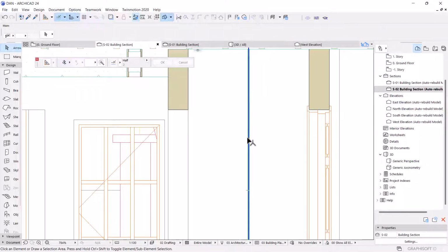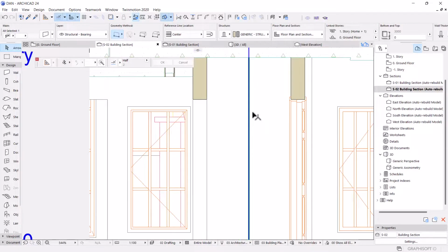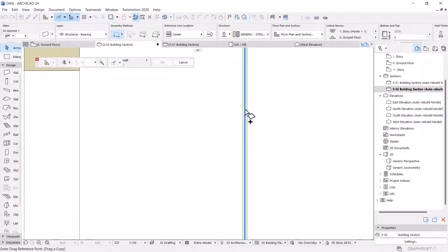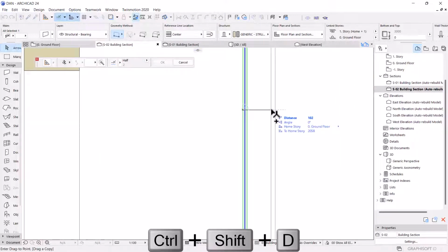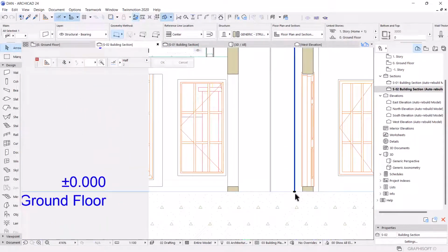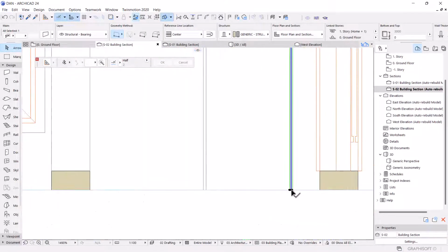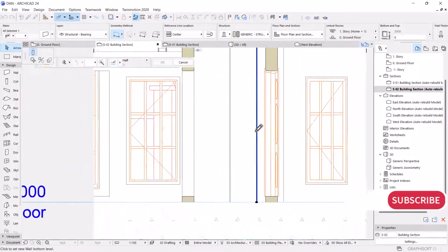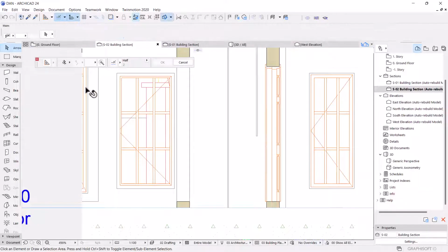Okay, so I can drag this one to the right. Let me drag from the center so that it is 900. The half of 900 is 450. 450, then I can try to shorten it. So you can draw this with the slab option or with any other option. Even the shell tool can do this.